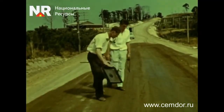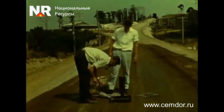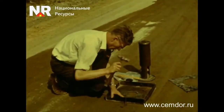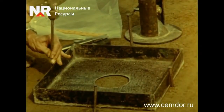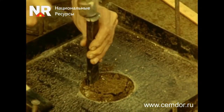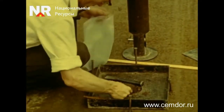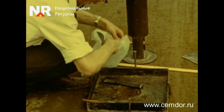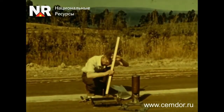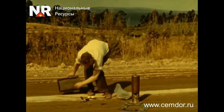The density of the compacted structural layer is determined by directly extracting a sample and sending it for analysis. The thickness of the structural layer is measured and the volume of the extracted material is determined by filling the hole with sand of known density.